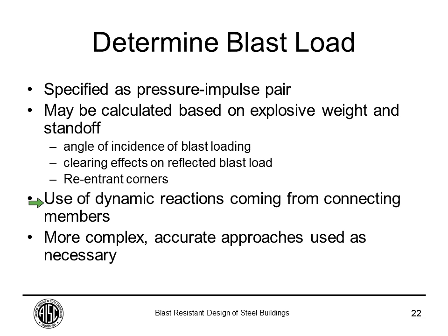Another way of determining the blast load for your component is using the dynamic reaction from the connecting member. And as needed, you may use more complex approaches, like if you have an internal detonation, you could use something like Blastex. It will calculate shock and gas pressures. Again, you want to pick the tool that best suits your needs. For most blast resistant design buildings, you're going to be dealing with a pressure and impulse pair, or an explosive weight and a standoff distance based on the site layout.